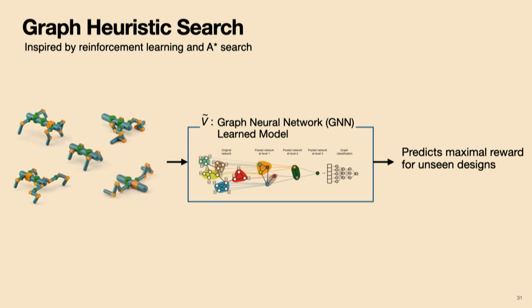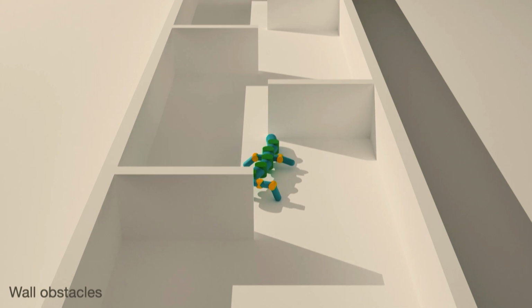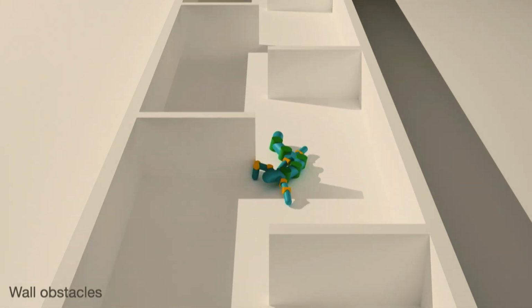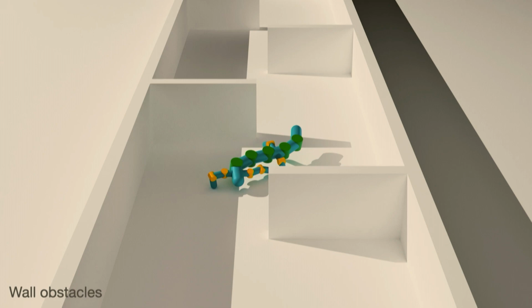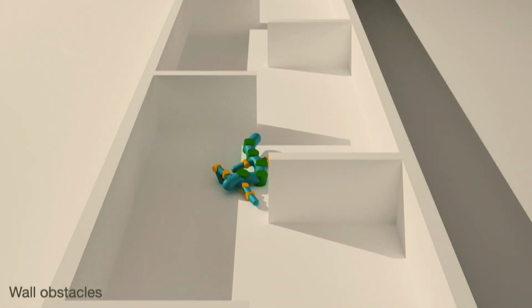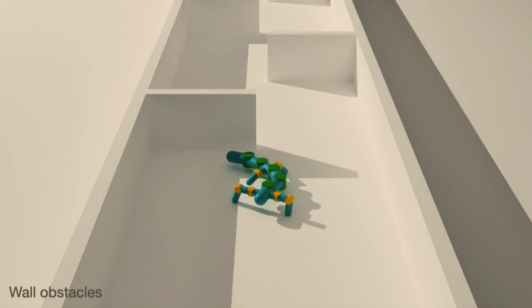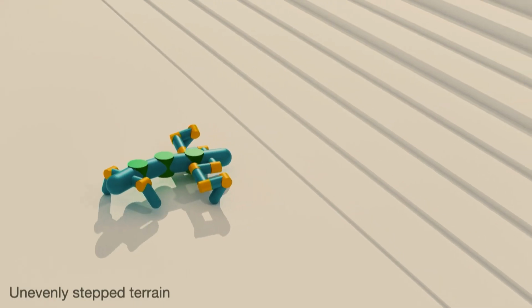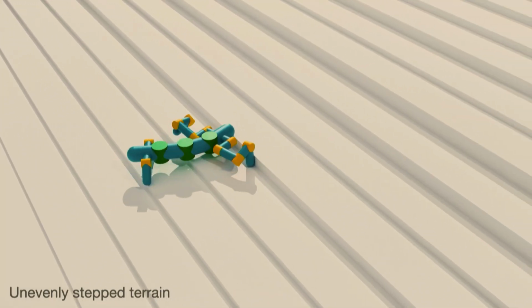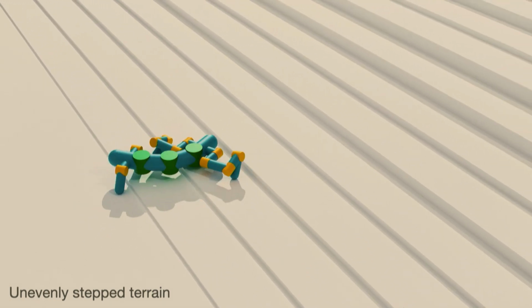Now, by using this graph heuristic search that we developed that works on graph neural networks, we are able to find structures like this one, for example, that is optimized for avoiding a set of wall obstacles. Now, an important thing to note here is that as a human, you would never manually design a structure like this. It's completely unintuitive, but it actually proves to be way more efficient than any conventional design that we see around. Or this one, for example, is optimized for an unevenly stepped terrain, which is one of the most challenging ones for robots to traverse. It has these front hooks for climbing and simple back legs to save the energy.